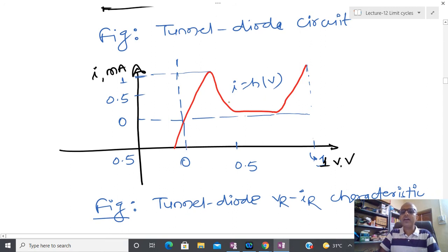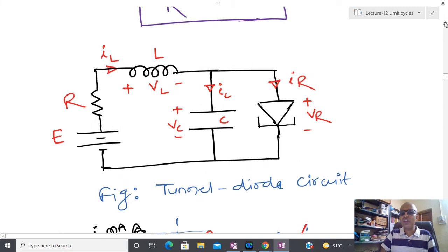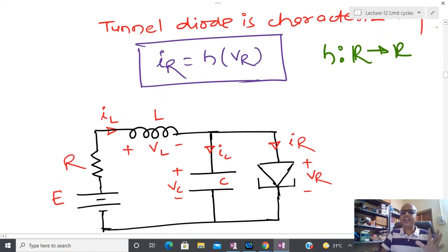Okay, and by increasing voltage, since current decreases, people interpret that as a negative resistance. Are you able to understand this point or not? Because in a general circuit, or a resistor kind of circuit, if we increase the voltage, then current increases. But what we found in this particular type of circuit is that initially the behavior is the same as a resistor, but after that, if you increase the voltage, then current decreases, and this portion is interpreted as a negative resistance. So that is basically the unique characteristic of this particular diode.